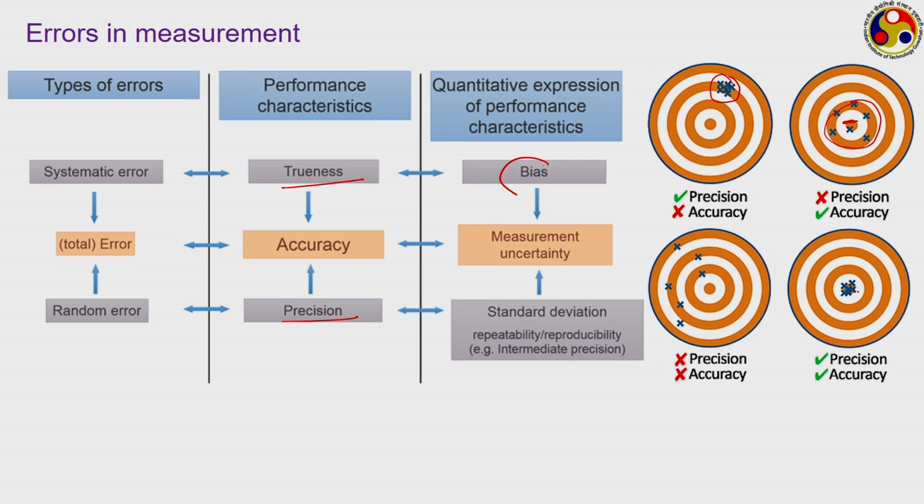We always want our result to be both highly precise and also true or accurate, but that is a very ideal situation. Most often than not, we have to deal with the scenario that it is neither precise nor very true, thereby affecting the final accuracy of the observation from both bias error and precision error points of view. And the total error present in a measurement is a combination of both.